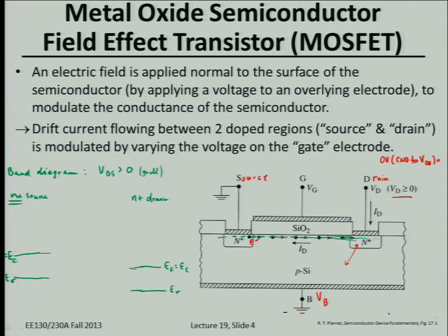But at what height do I draw the energy band diagram? Yeah, that's right. It depends on the gate voltage. So let's draw for VG equal to 0 for now. Typically from your homework, do you remember what the threshold voltage is? 0.7. Not that high anymore. But at VG equals 0, the surface is typically depleted. So it will still be somewhat p-type, right?